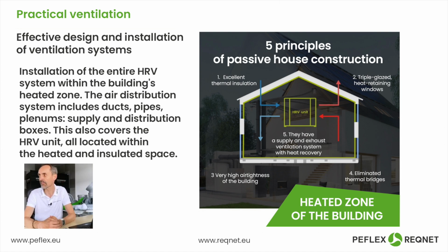Proper installation of a ventilation and heat recovery system means the entire system is placed within the warm zone, that is, the heated and insulated area. If we ensure that, then the only remaining issue is noise, which really comes down to limiting the air speed in the ducts.